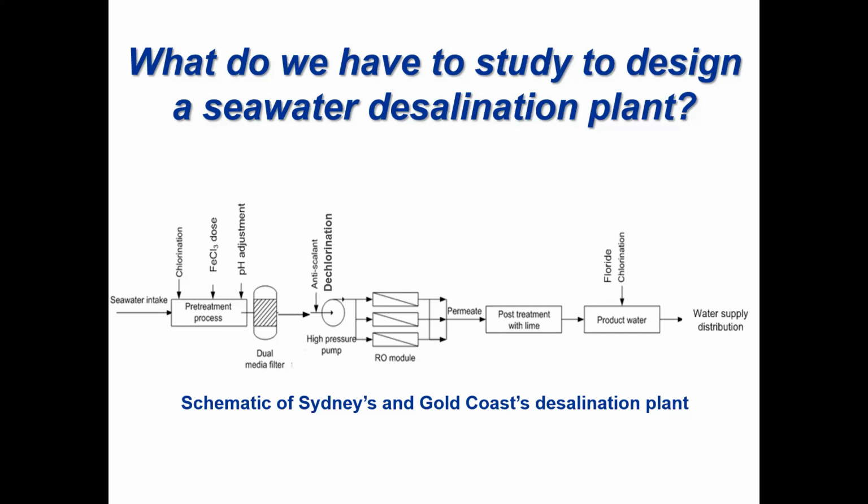And then we are dechlorinating here again, because the reverse osmosis membrane is a polymer. Chlorine is the oxidant, so oxidant meets the polymer. It slowly damages the polymer layer, right? It's degrading. So your polymer active layer in the membrane is slowly removed because of the oxidation process.